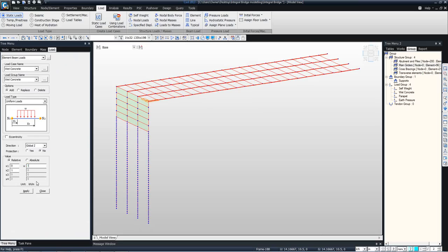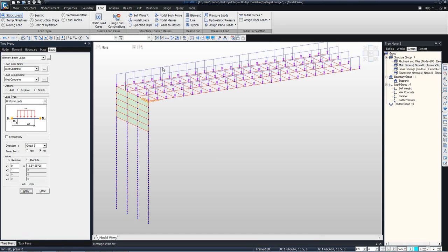And we can also write down a function to calculate the wet concrete loads. So I'll just use a simple multiplication function to calculate the effective wet concrete load on each main girder. So 3.5 width of the slab, effective width, depth of the slab into material density, which is 25 for concrete, and just click apply. So concrete dead weight is applied on the steel girders.